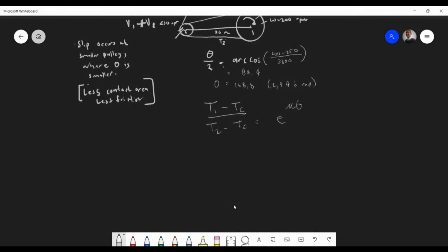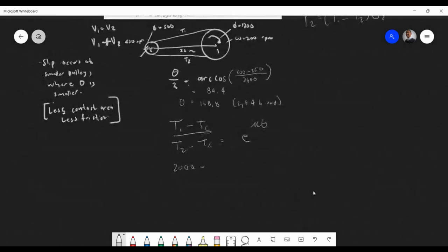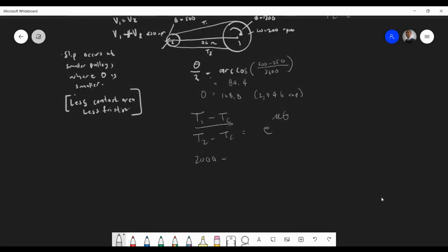Okay. So you're limited to 2000. And of course, now we can calculate Dr. Raman's favorite parameter, the centrifugal tension. The Tc is equal to mass times velocity squared. Easy to remember, just think of rho times velocity squared, rotational hoop stress. That's what I remember. We've got a mass of 0.9, we times this by the velocity.